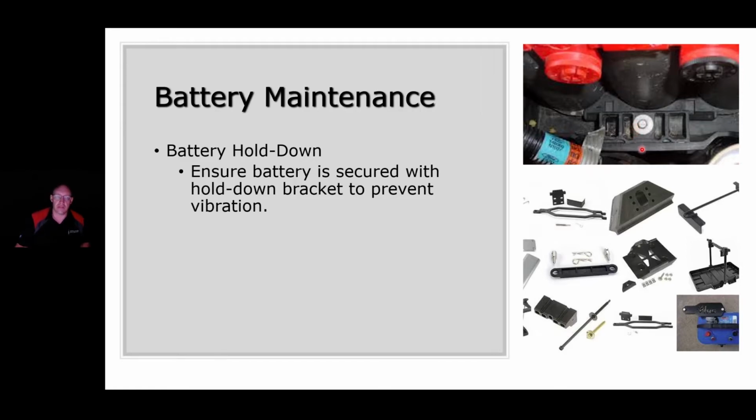When battery hold downs are broken or missing or corroded and damaged, they have to be replaced, guys. You guys are responsible as a professional technician, as a professional individual. You have the responsibility to notify the customer that this stuff has to be done. It's a safety factor.